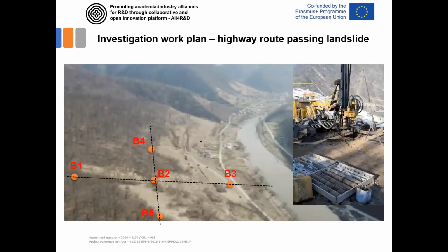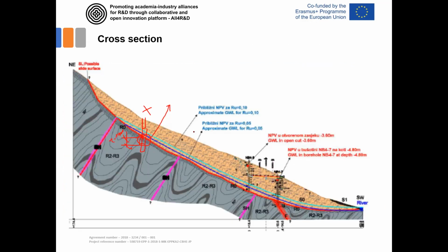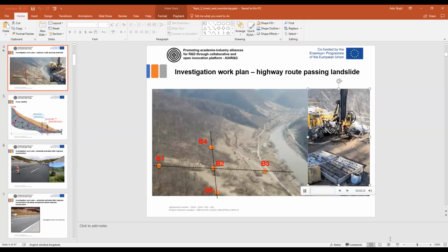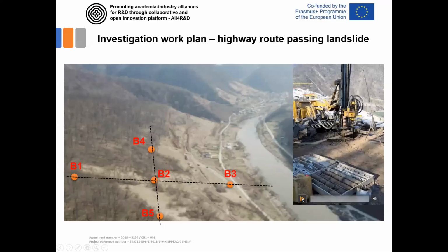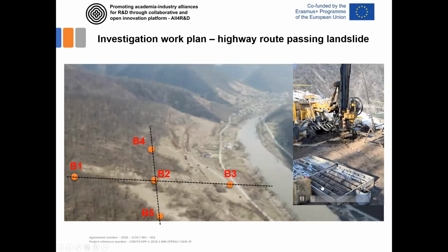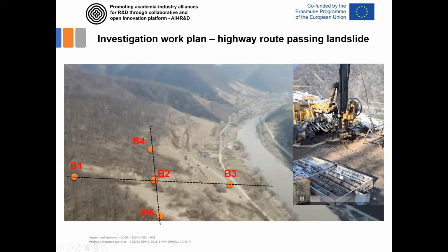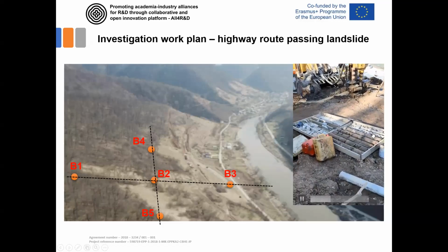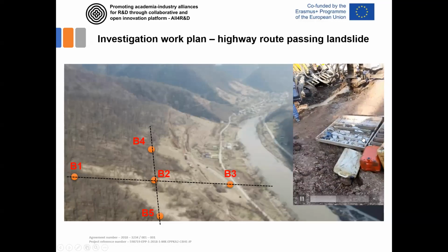Here, it was a much bigger problem. Here, really, this is soil-like material for 20 meters, and then you have a very good quality rock similar to the one you see here. Practically, this is the soil profile you have on this landslide. There is 20 meters of soil like this, and then you have a rock. It's more than obvious that we have sliding here, if sliding really is an option.